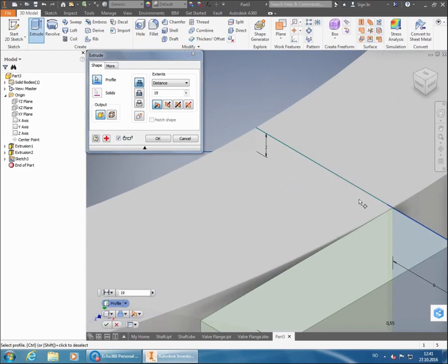you see that the extrusion is curving away from the ring. So I need to also manage to mark the small thin rectangle that is on the inside there, the 0.55. And now we see that my extrusion is fused all the way over here. I haven't put the correct width yet, so it's way too big compared to what it's going to be, but it illustrates the point pretty clearly.